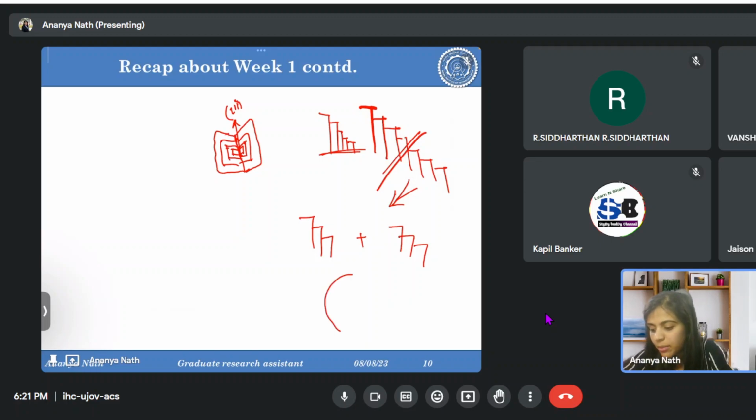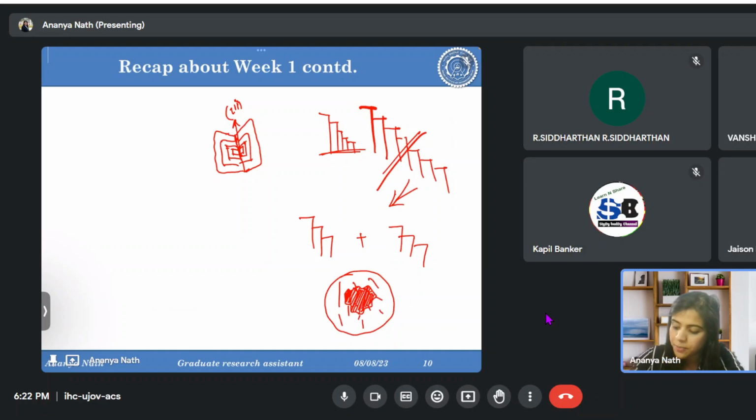Inside a particular aluminum alloy, this is the primary aluminum, and if a small primary silicon has grown like this, it is introducing a lot of brittleness inside the metal. If we can go from this to this, where there will be small silicon growth throughout the whole metal alloy, it will be beneficial for us.